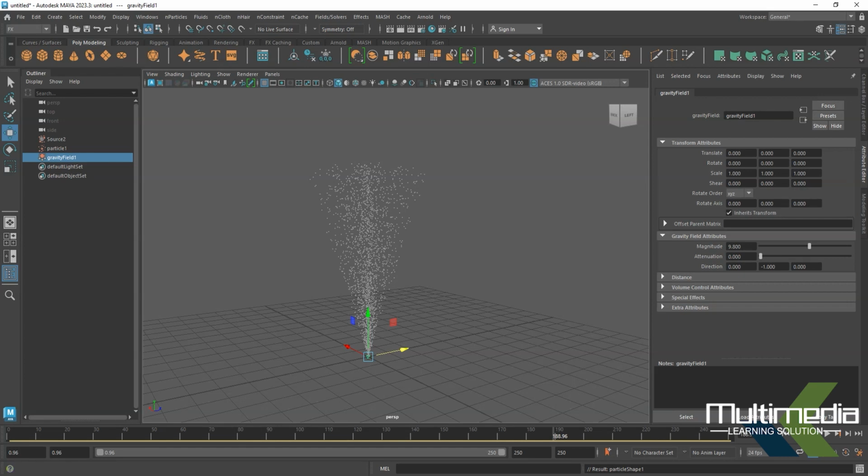Now you will see gravity is by default 9.8 magnitude. Now if you want to increase or decrease the value of the gravity, meaning magnitude, you can directly change it from this option. Now the thing is, I want to play from 0. I just say this, it is going down.